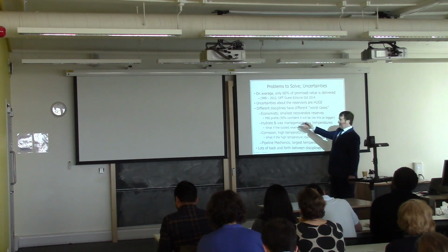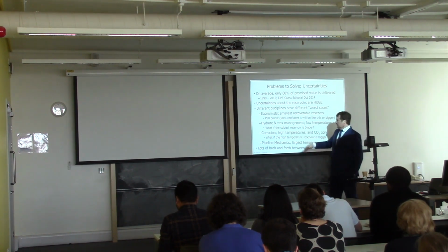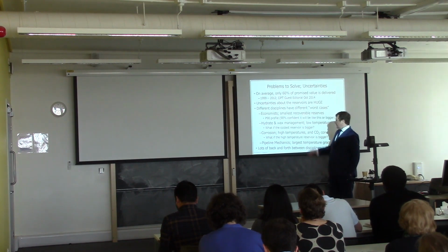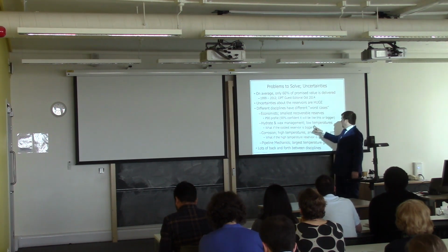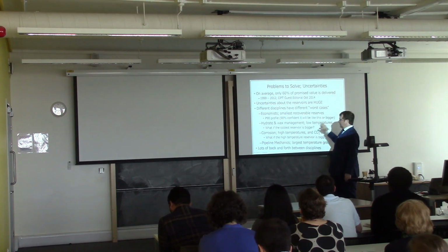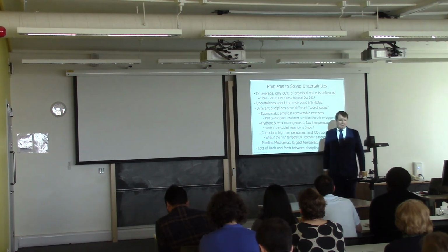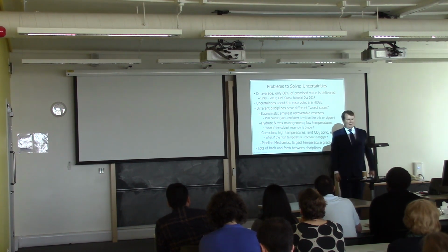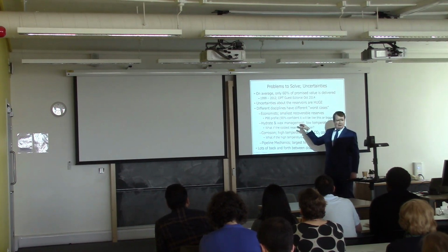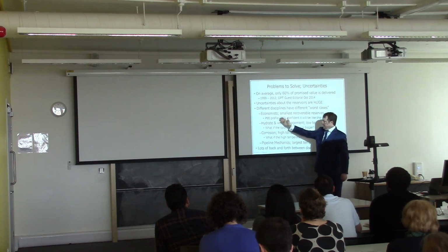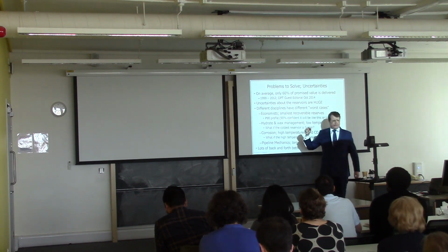But it's not necessarily conservative for all the engineering disciplines. For example, hydrates and wax are normally avoided by keeping it hot. So what if in a system a hot reservoir and a cold reservoir are blended together in a pipeline, and we're worried about low temperatures, what if the coldest reservoir is the biggest? Well, these guys go, Martin, bigger reservoirs are better than smaller reservoirs. But what if my cold reservoir is bigger? We end up producing a lot more from it. My pipeline is now colder, I'm now closer to the wax problem. So we have to think more than just, I'll design to this P90, that's the worst case, everybody.